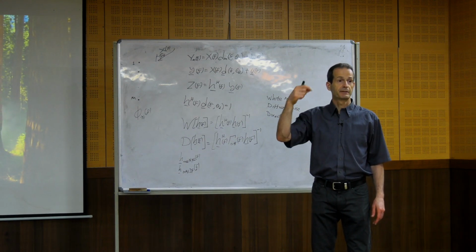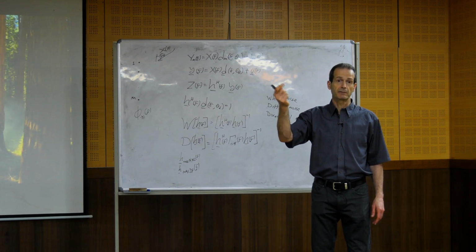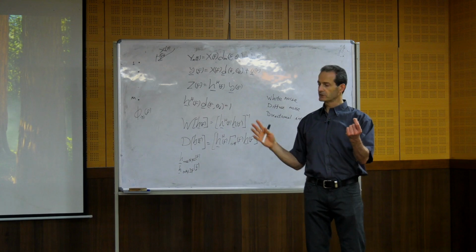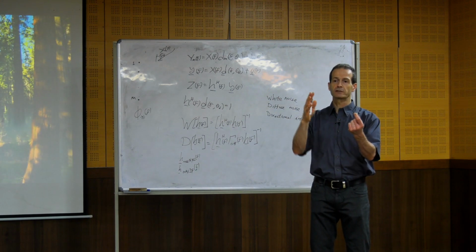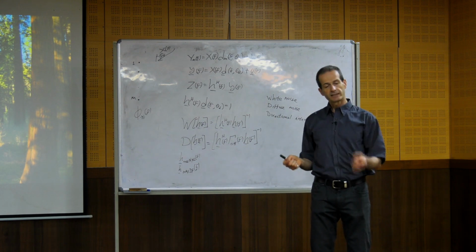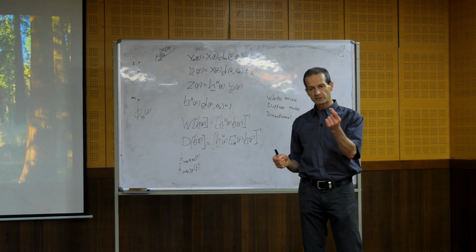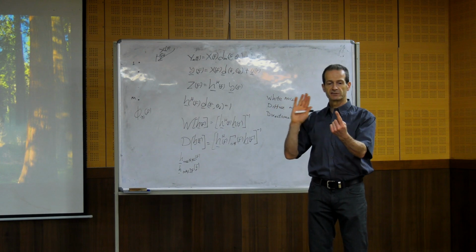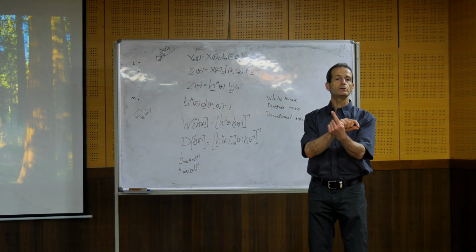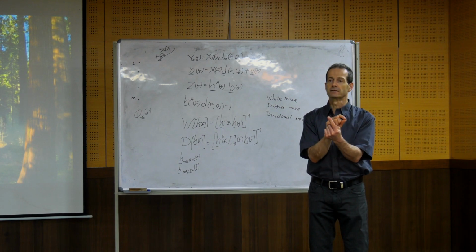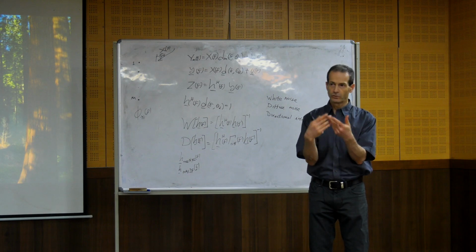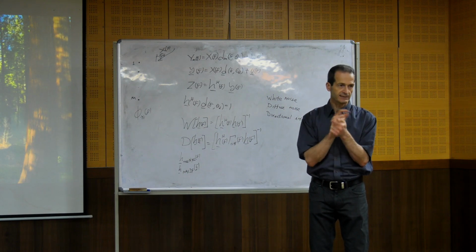Sensitivity means the magnitude sensitivity, the magnitude gain, because what is a sensor? A passive sensor, for a propagating wave, for example acoustic or electromagnetic with antennas, whatever, is something that receives a propagating wave and generates at its output an electrical signal. But this transform or gain depends on the sensor.